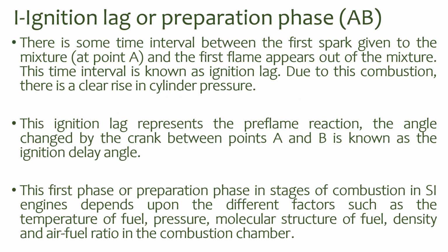The first stage is called the ignition lag or preparation phase. There is some time interval between the first spark given to the mixture and the first flame appearing out of the mixture. This time interval is known as the ignition lag. Due to this combustion, at point B, there is a clear rise in cylinder pressure. This ignition lag represents the pre-flame reaction. The angle changed by the crank between the points A and B is known as the ignition delay angle.